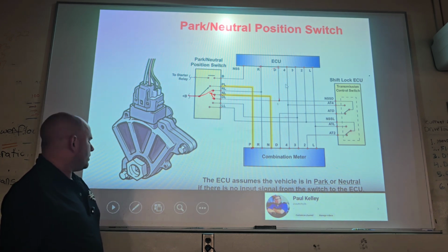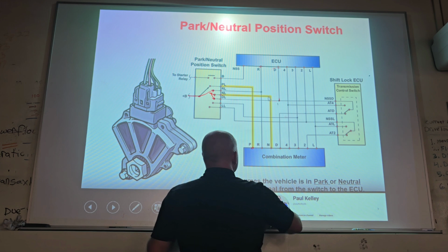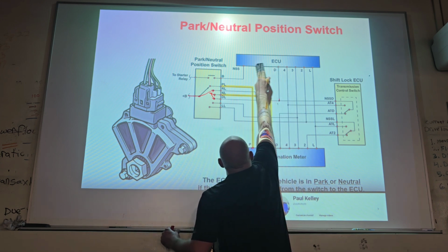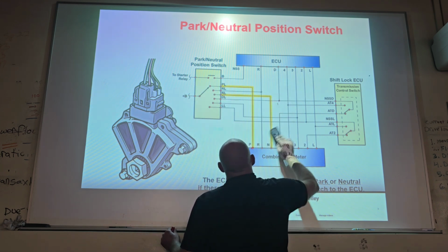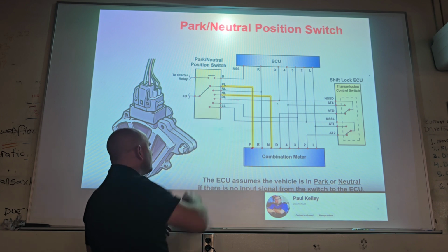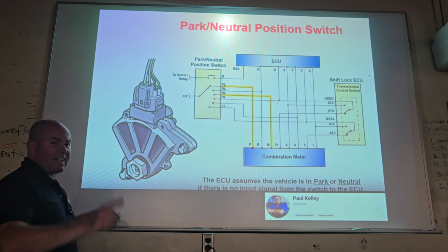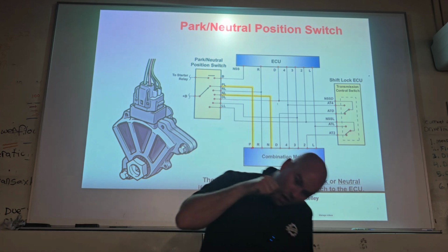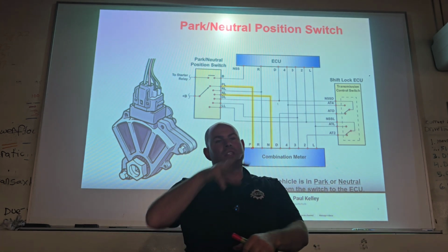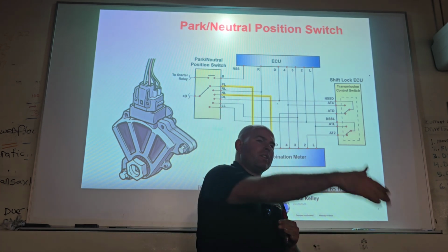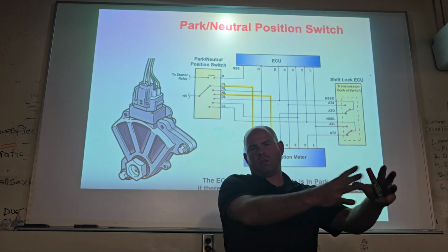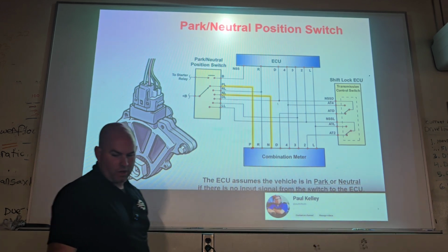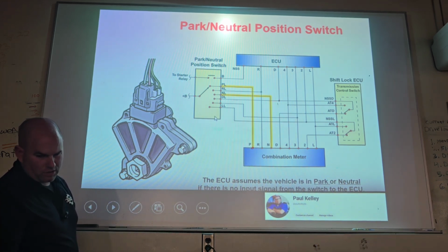Cool. So your ECU needs this as an input. This tells the ECU what gear position your actual shifter's in. Who remembers where that switch is? Yeah, it's not at the shifter. Most people start looking at the shifter and they're like, oh, where is it? It's not at the shifter. The shift cable moves way out to the transmission. That switch is going to be at the transmission almost every time. Okay? Still do some diagnosis there.